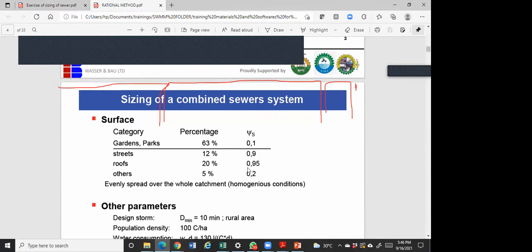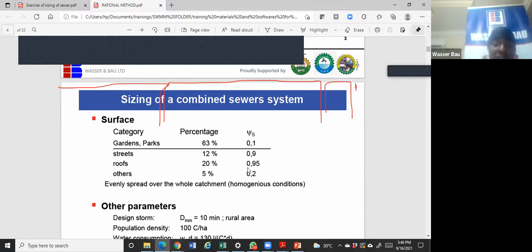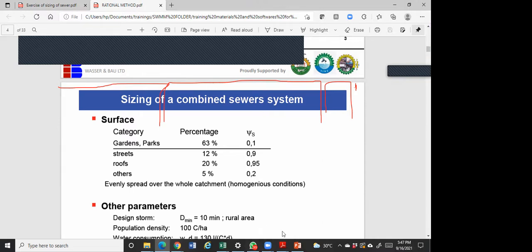coefficient. Yeah. For instance, in Abuja, Maitama might use 0.68, another area 0.75, but Lugbe 0.5. Then Kuje 0.4, Gwagwalada 0.3, because Gwagwalada is a farm area, a green area, a farmland. Then Lugbe and Kuje are upcoming areas, so I can say 50-50, 50 built, 50 unbuilt. When you come to Maitama and Asokoro, I will be going towards 1, meaning that every stormwater will go into the drain. That's just the layman's definition of that coefficient. The place is completely built up.